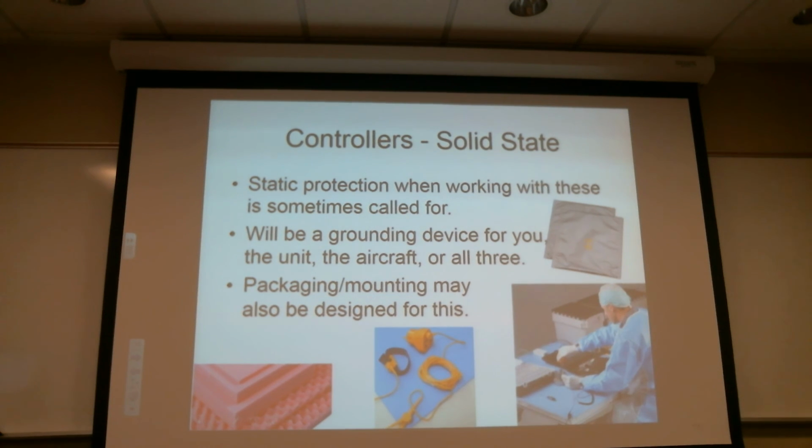The static protection, though, is the blue mat and the little coiled strap that's attached to it and to his wrist, or the example that you see over there. Definitely, you're going to want to use that. Now, this was far more of a problem 20 years ago, 30 years ago. Nowadays, most circuit designers have done a pretty darn good job of making their stuff bulletproof.